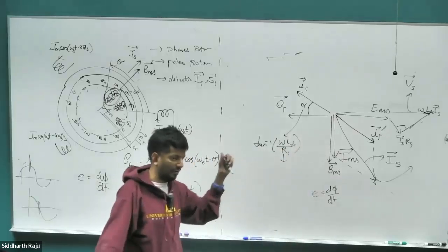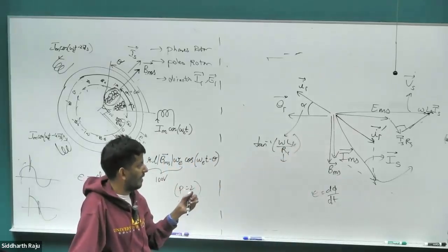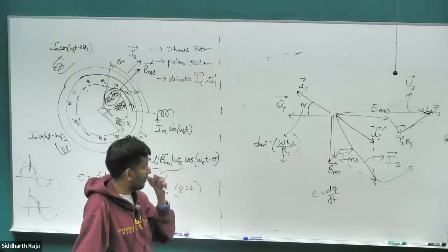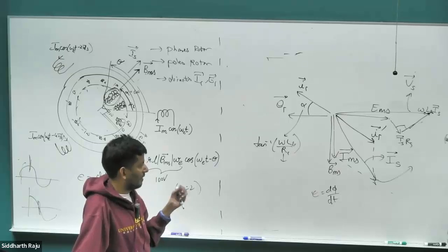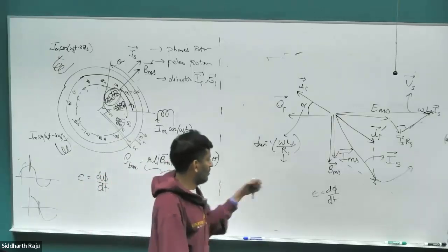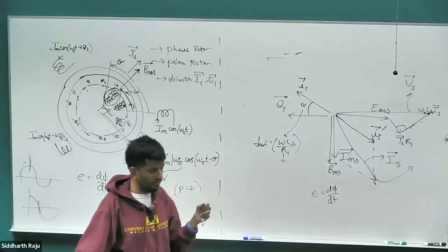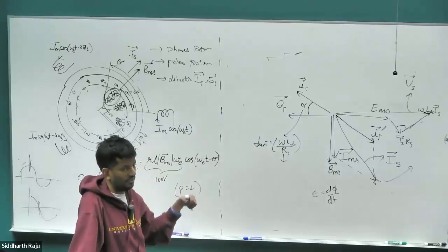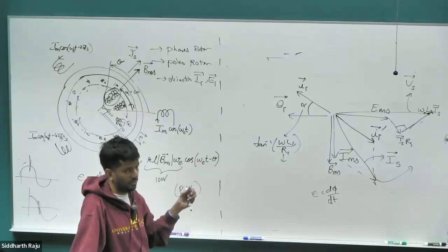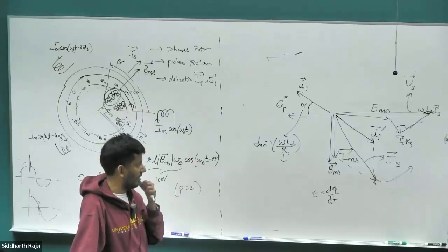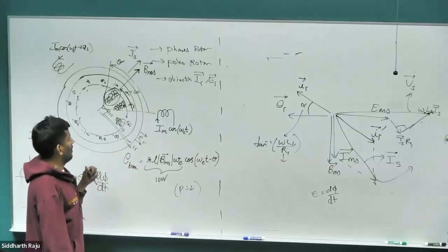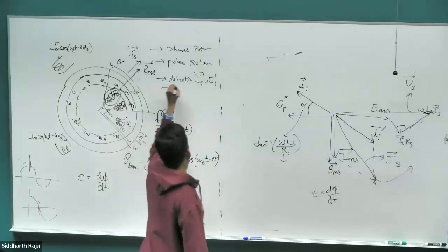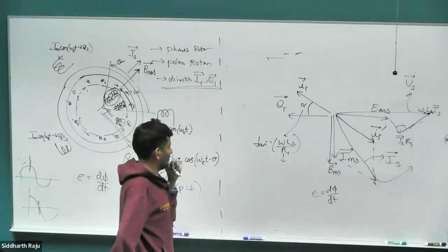Without having to go back, like for a permanent magnet synchronous motor, where we looked at the magnetic field in the air gap and tried to figure out the torque by doing integrals over the air gap field. But none of those complications are necessary because we clearly showed when we did it for the permanent magnet synchronous motor that just by looking at the space vector, you can figure out all of those relationships. Right? All linear operations get translated when you do space vector transformation. Non-linear operations do not transfer though, right? Okay, so we have addressed one question, the direction of ID.